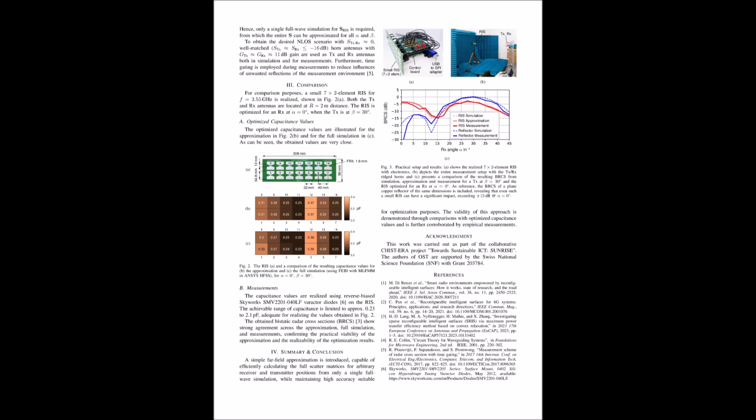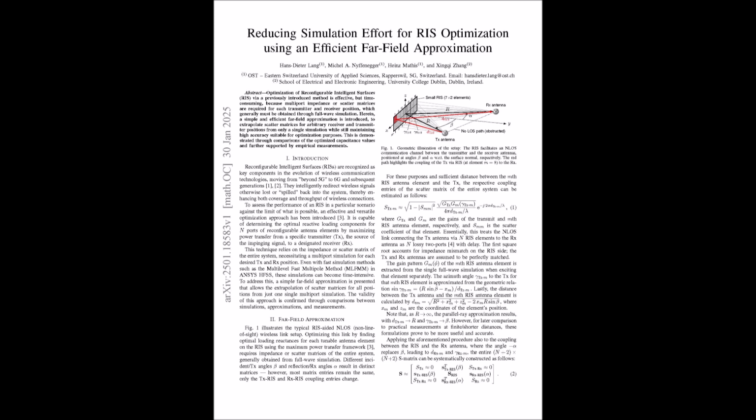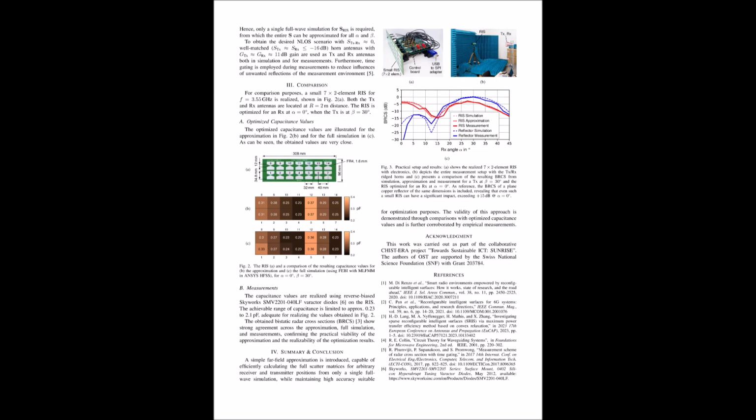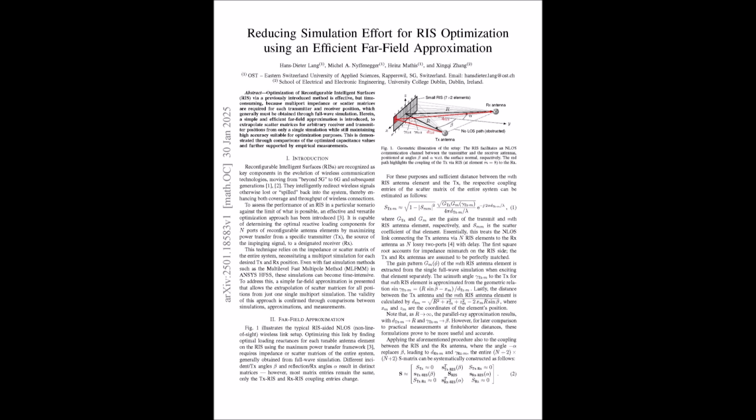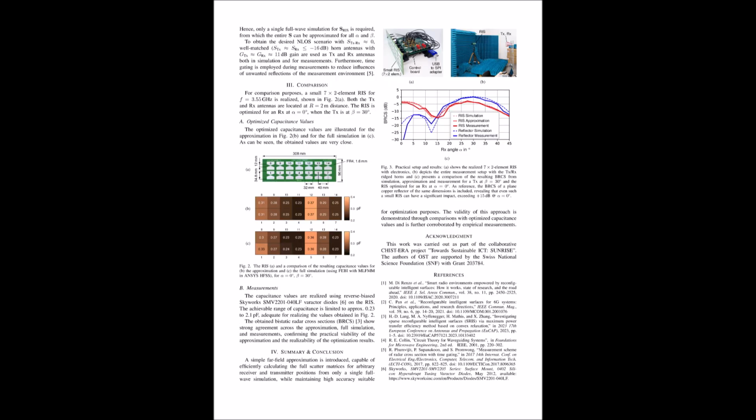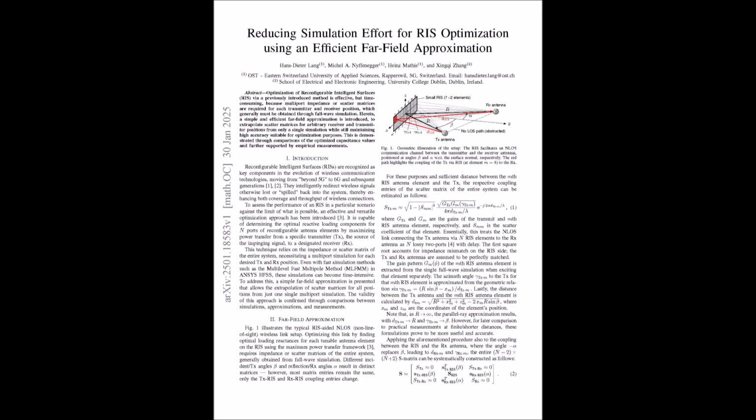You've got it. So in a nutshell, this entire equation 1, despite its seemingly complex form, is elegantly capturing the essence of how a signal travels from the transmitter to an individual RIS element, taking into account factors like impedance mismatch, antenna gains, signal attenuation over distance, and the crucial phase shift that occurs during propagation. That was an incredibly insightful breakdown. I feel like I have a much deeper appreciation for the complexity involved in accurately modeling how these signals behave. And what's amazing is that this equation manages to condense all of that complexity into a relatively compact form.